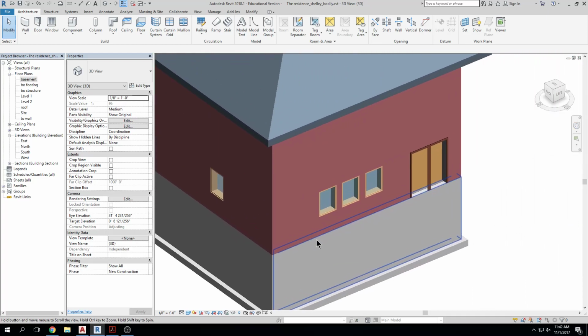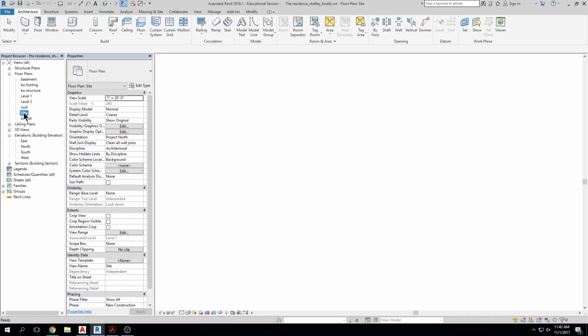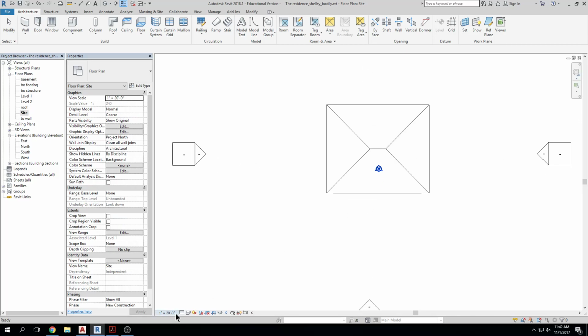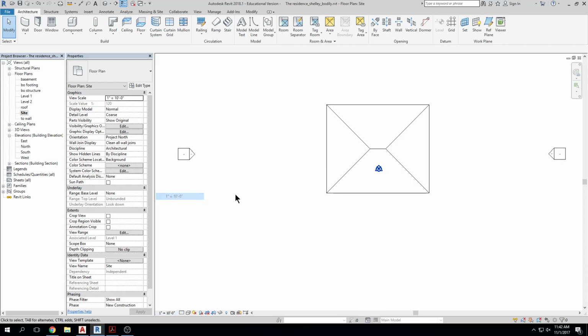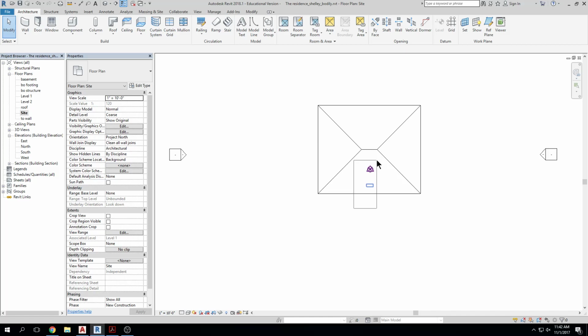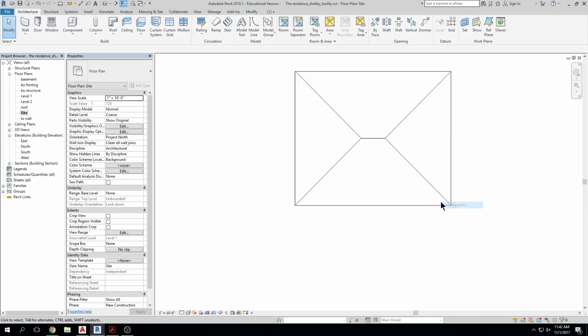All right, so we have our foundation walls. You can use a line on them. They can be a little bit of work, but once you have them in place, they function very well. Let's add some topography. Let's add some topos into this little project. I'm going to go to my site plan, and I want this to be 1 to 10. Where is it? 20. Oh, yeah, there it is. I'm going to do a blue selection window, grab my base and survey point and hide those for now.